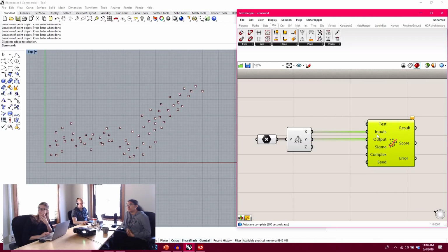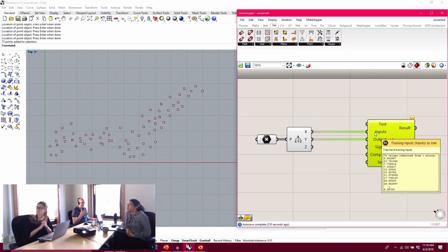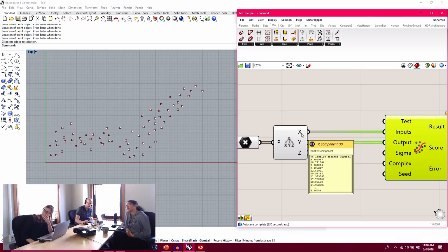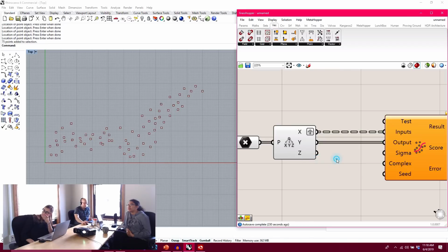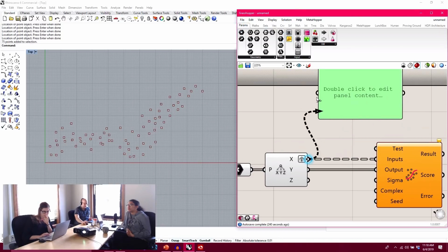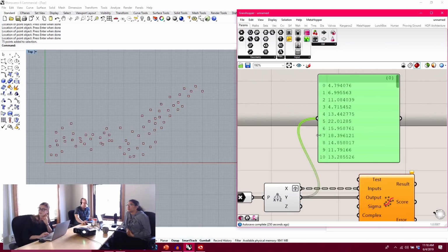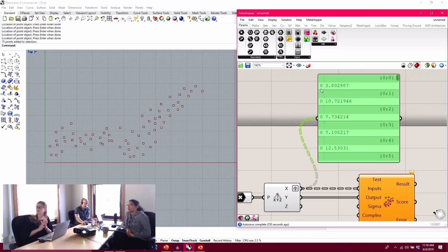Now, this isn't quite going to work going straight in like this because your inputs might have multiple dimensions to them. It may be that you want to do x and y and then predict z, for example, as a nonlinear function. So there is an important thing that we need to do here, and that's graft the output x. So it's going to graft those points, and what we can see when we inspect this data structure, it's not going to be so apparent here, but you have all your x values organized in their own tree branch, and these are a flat list of single outputs. But you might have other characteristics and criteria here. So for this first data point, you could have a list of 10 things, right? That helps to predict the output or something like that.